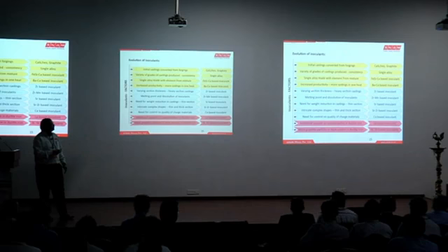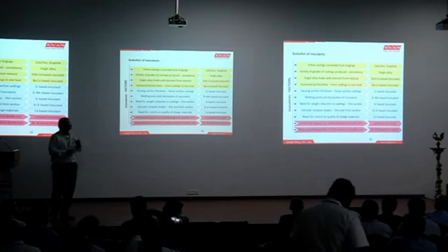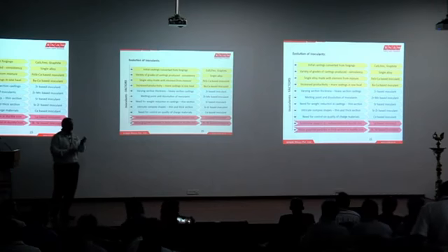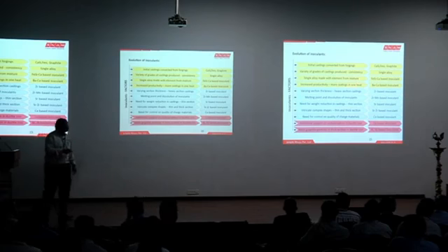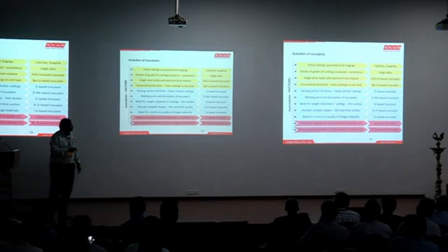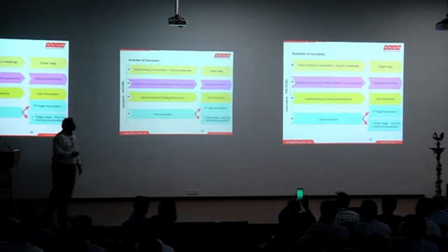And when productivity increases, in this scenario, if the castings were performing well and they wanted more castings, and a productivity requirement came up, say you wanted to pour more boxes, more castings, so long pouring time, sustainability of the property of the liquid metal and casting throughout the time, barium or calcium inoculant would have come up. And when varying section thickness came up in heavy sections or thin section castings, zirconium inoculant. So these are some of the requirements and evolutions of the casting industry, and how these inoculating elements would have appeared in relationship with the evolution of the casting industry.